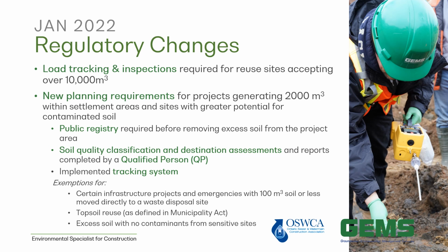There are exemptions, however. Some infrastructure projects and emergency projects where it's 100 cubic meters of soil or less can be moved directly to a waste disposal site, and they don't need to follow those new changes coming out in 2022. Another exemption is for topsoil reuse, but that needs to be defined in the Municipality Act. Also, excess soil that has no contaminants from sensitive sites is exempt from the new planning requirements as well.